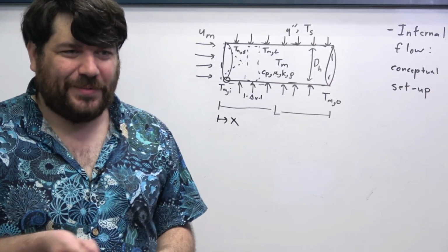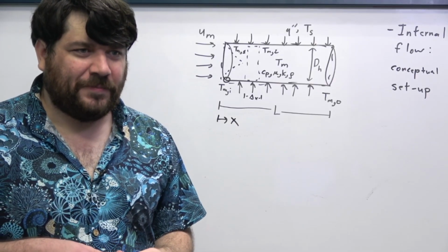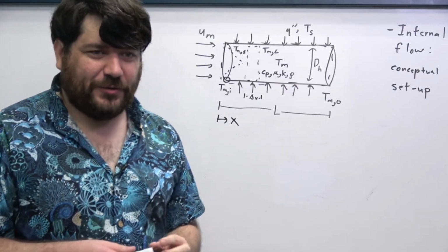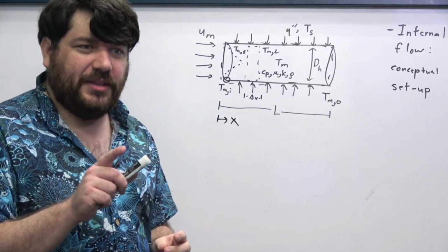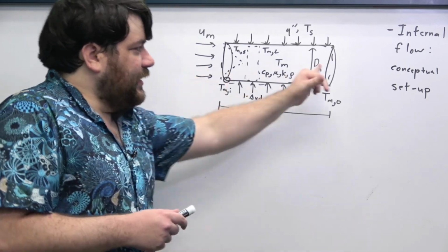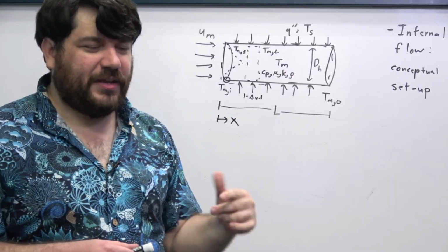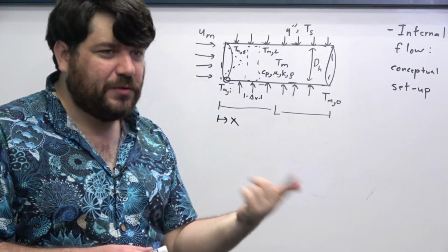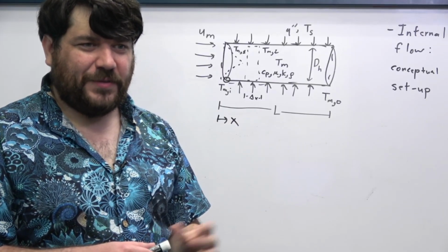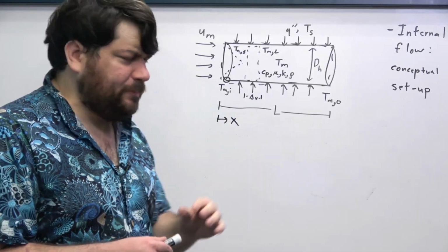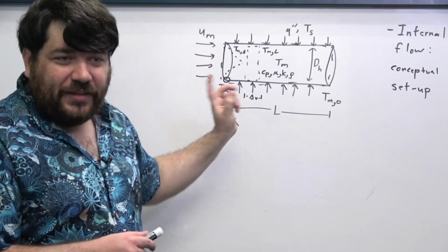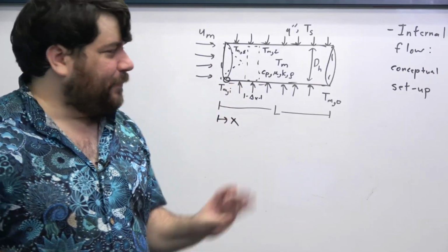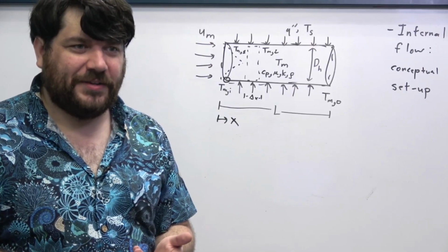Also, one other thing I should mention. When does turbulence occur inside of internal flows? Here it's actually going to matter. You'll see that it will matter in the next lecture when we actually start doing exercises. But the whole point is that in internal flows, rather than in flow past flat plates, turbulence occurs everywhere once you get past a critical Reynolds number. So before, the whole idea was, it always starts off laminar in flow past flat plates, and then eventually, once you get past a specific distance, the flow will become turbulent.